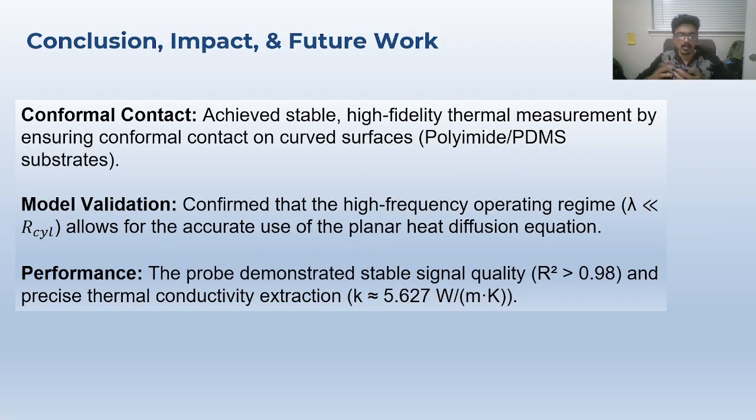So the concluding part, and the future work that can be done: conformal contact was achieved, and high fidelity thermal measurement on curved surfaces was achieved using PDMS substrates, and model validation confirmed that the high frequency operating regime allows for the accurate use of the planar heat diffusion equation.